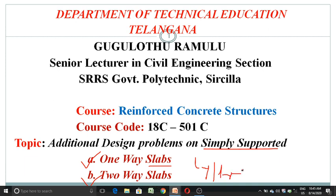If the ratio Ly by Lx is less than or equal to 2, I can say this slab is said to be a two-way slab. If this ratio is greater than 2, then we call this slab a one-way slab. Then we have discussed that in two-way slabs we have two more types: restrained slabs and unrestrained slabs. Restrained slab means the corners of the slab are not lifting up, and unrestrained slab means the corners of the slab are free to lift up, and we have seen the design of those also, right?